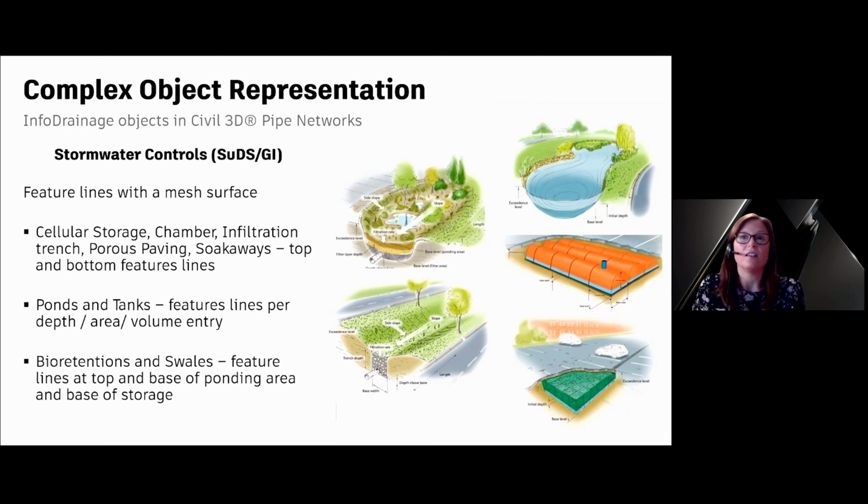Now, these feature lines can be edited for round tripping. So we can change the shape of that feature line, and we can actually change the levels as well to make them deeper or shallower. And they're, again, maintained with the round tripping, they're tagged.